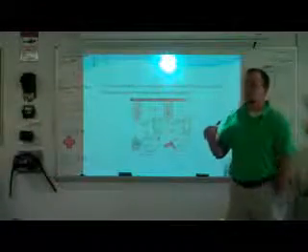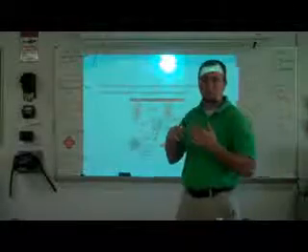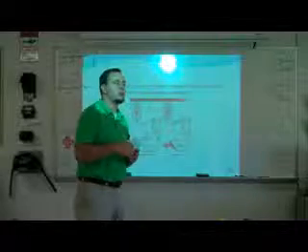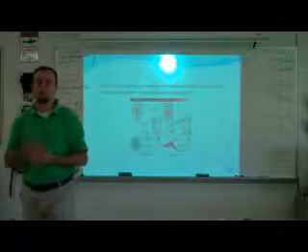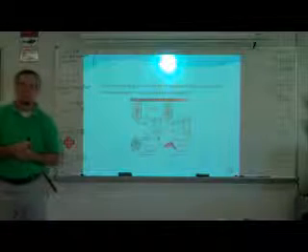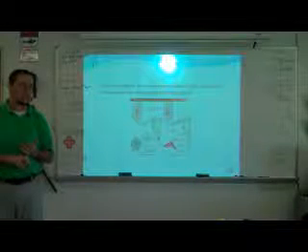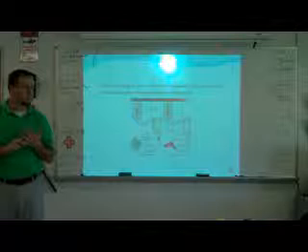So remember all of your loads. If you're talking about a motor pulling a conveyor and you overload that conveyor, you're going to cause that motor to work harder. It's going to pull more amps until it trips out. That's a bad deal.